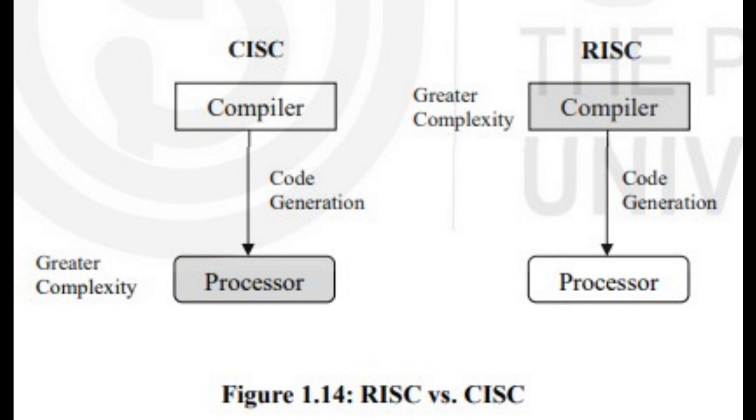Look at the screen. CISC emphasizes the complexity of hardware. The RISC emphasizes the complexity of the compiler. The RISC philosophy is based on 4 main building blocks. 1. Instructions. Number of instructions has been reduced in RISC. An instruction of RISC is executed in several segments. Instruction execution is overlapped in these segments, called pipeline segments. Each segment takes about 1 clock cycle time.